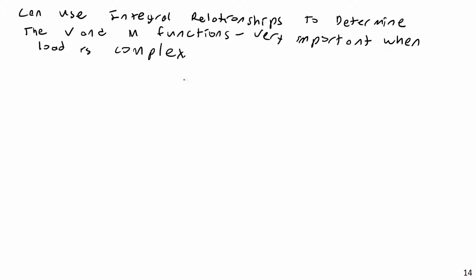The load is rather complex, and not necessarily complex in the sense that there's a whole bunch of different zones and discontinuities and things like that. That's actually done best by the method of inspection, which I don't know if we're going to touch on this semester. But when I say complex, I mean mathematically complex. Like if you have a nice constant value load, method of sections is probably the best. If you have a linear load, well, even method of sections there is pretty decent. But if you have very complex loads, like I gave you a sinusoidal load or something like that, that would be a pain in the butt to do via method of sections. So it would be a lot easier to deal with via integration.